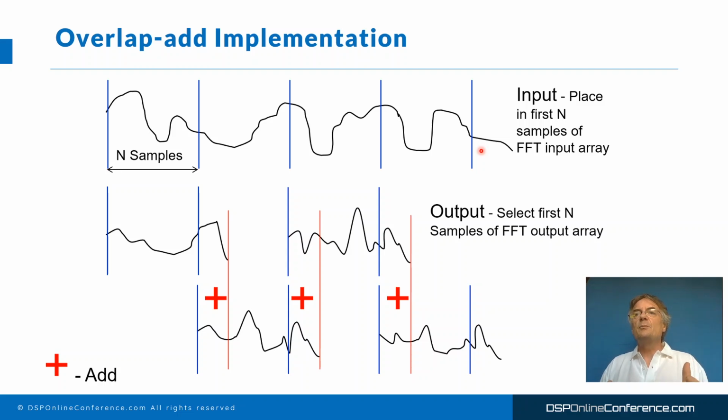So n input time domain samples, m input coefficients, convolve together, the output length is n plus m minus 1. So the output length is always more than the input length. That's how block-oriented convolution works. So this is why we have to do the overlap and sum of the data so we don't miss anything.